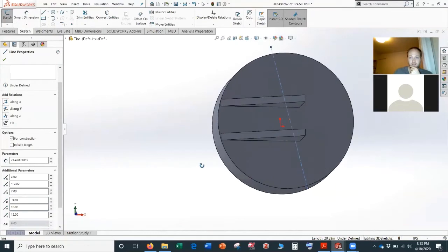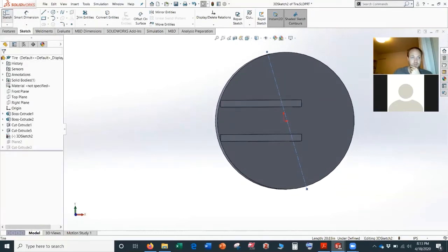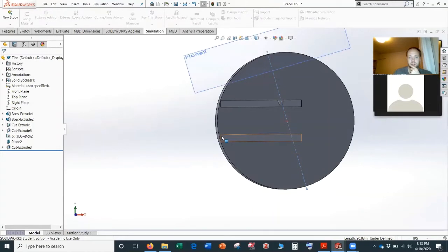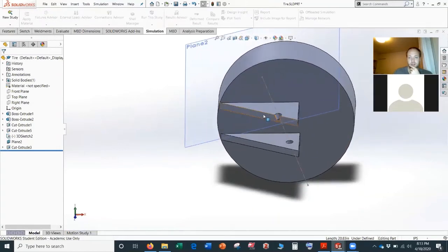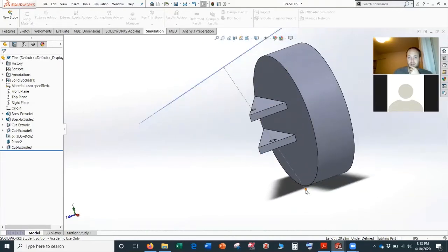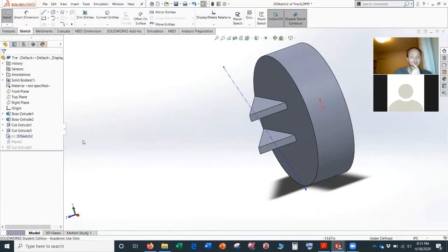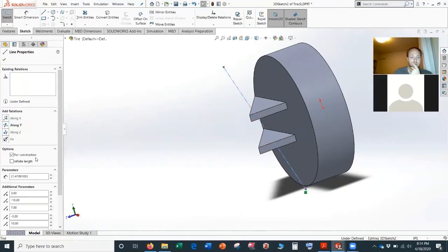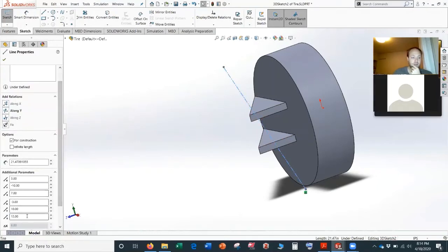So okay. So now if we look in this direction, I'm going to exit my sketch, and you're going to see top ball joints here, lower ball joints here, right? In this case, I've kept a little bit of kingpin inclination as well. Although maybe we can get rid of that for now. Let's simplify so we can look at just one effect and not 2 effects. So I'm going to take this. I'm going to put this straight up and down. So we'll put this at 7.